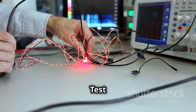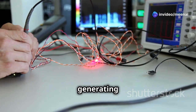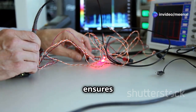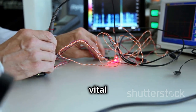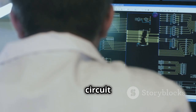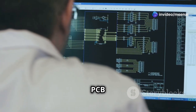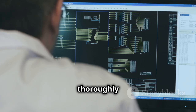The watchdog timer test. Simulate a system hang and observe the watchdog timer generating a reset signal. This test ensures that the watchdog timer can detect system hangs and trigger a reset, which is vital for maintaining system stability. Debugging tips. Double-check your circuit design, component values, and PCB layout. Small errors in design or component selection can lead to significant issues. Reviewing your work thoroughly can help catch mistakes early.